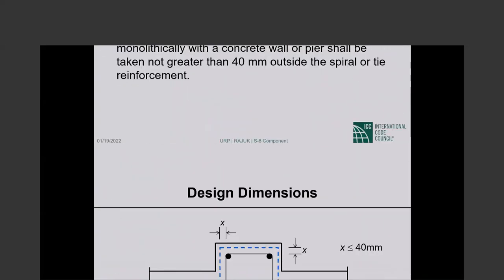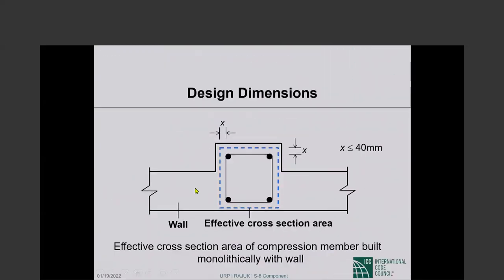And the other situation, probably more common, we call them pilasters, a column-like element built as part of a wall. Then the column section is taken as shown in this particular picture. Okay, ACI 318 is very specific that part shall be designed as a column.